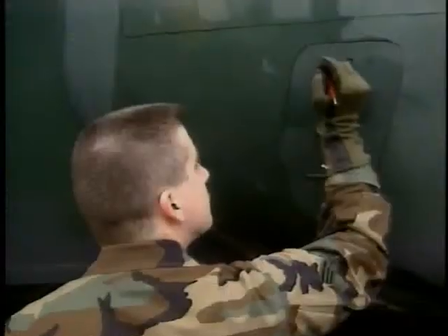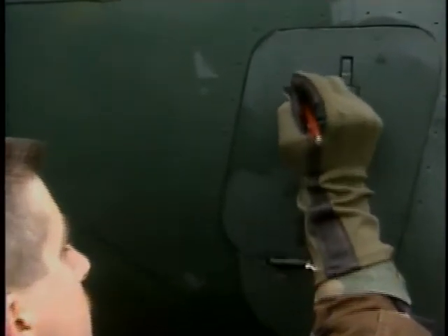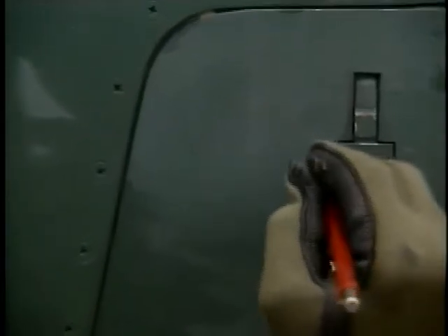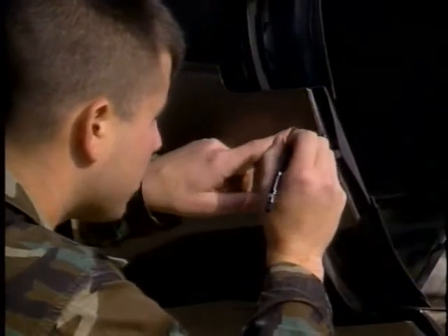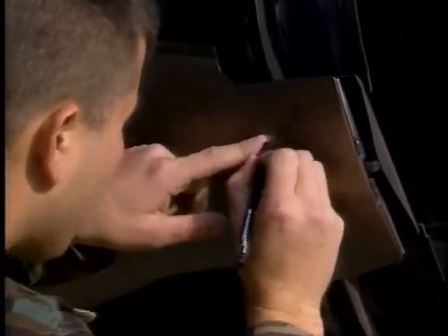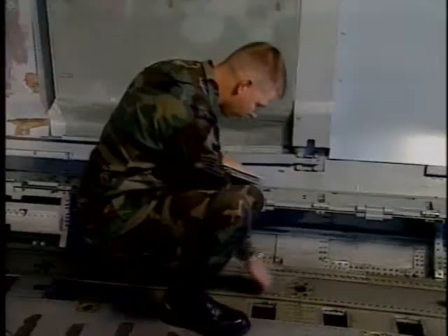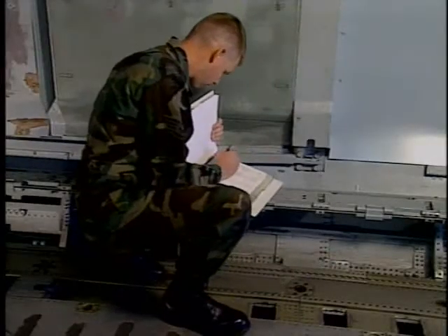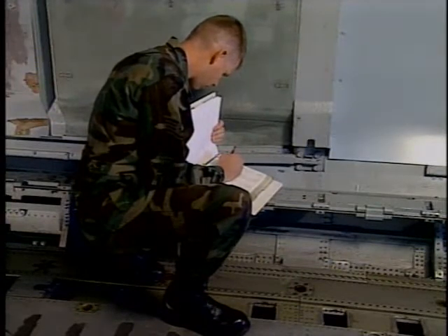failures. Using graphite marking media such as lead pencils for marking on any metal surface can promote accelerated corrosion. Chalk or grease china markers are the preferred method. A lot of damage is caused by cargo pallets and the tie-down chains used to secure them. Take the time to report these types of damage before they develop into bigger problems.